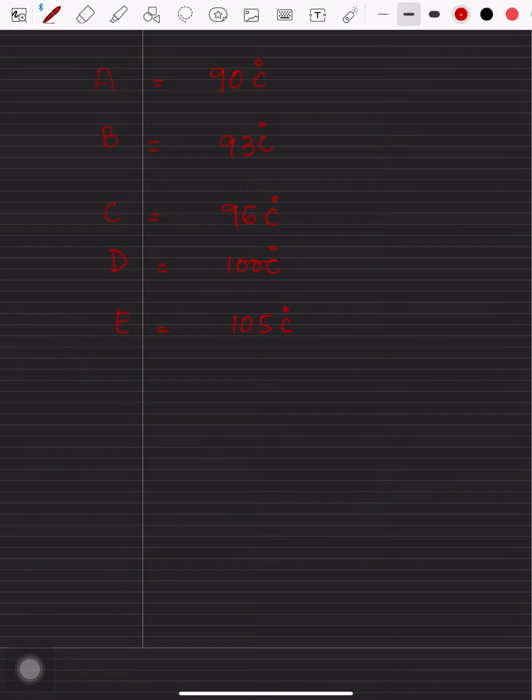All right. Now, what I'm telling you right now is this, that in this case, for example, at 90 degrees Celsius, what will happen at 89 degrees Celsius? Nothing will come out at 89 degrees Celsius. When the student will know that A is now coming out? At the temperature of 90 at the thermometer, the receiver flask will start receiving fraction A. All right. The next question which the examiner is usually asking is this: how will the student get to know that all fraction A is removed? When the temperature on the thermometer will be more than 90 degrees Celsius, it will give us an indication that all A is removed.